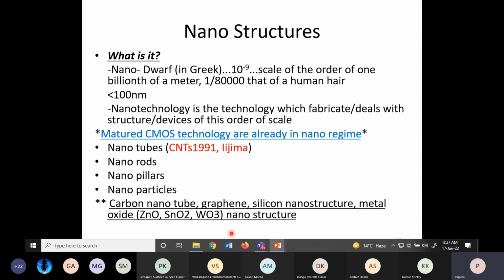High K dielectric, because there were leakage current and reliability issues of the gate oxide, and so forth. There were different short channel effects, and the performance of the silicon based MOSFET degrades, and then people thought that we would not be able to move on with silicon, and they started doing research on using different materials, because these materials have some advantages compared to silicon, right?